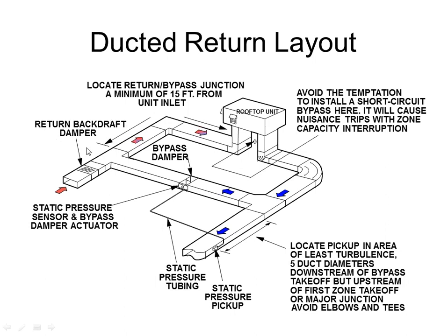You can possibly run into issues where, when you are bypassing air through this unit, this bypass damper, if you don't have a backdraft damper, you can actually leak air out of your return diffusers. And that is not good, especially when you have 55 degree air coming out to your zones and coming out of your return dampers, your return registers, I'm sorry.